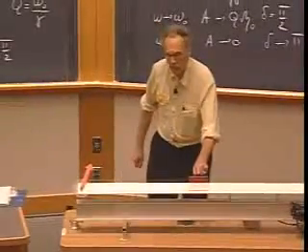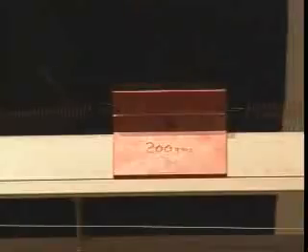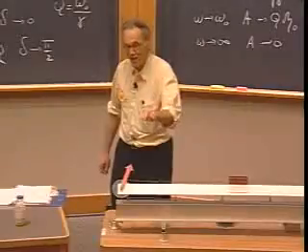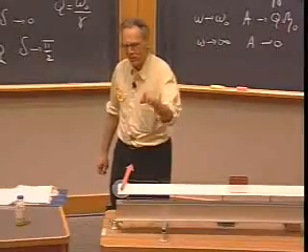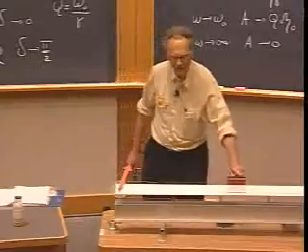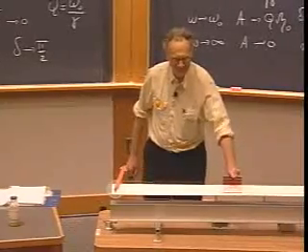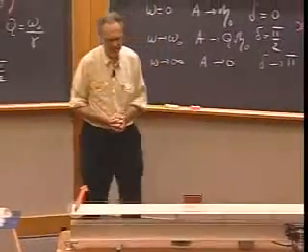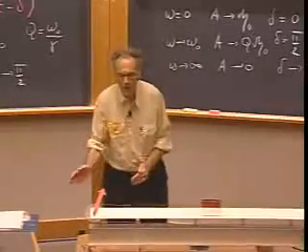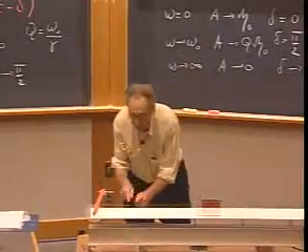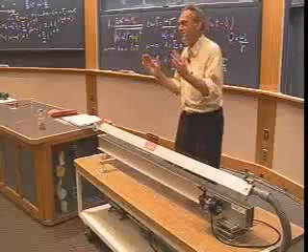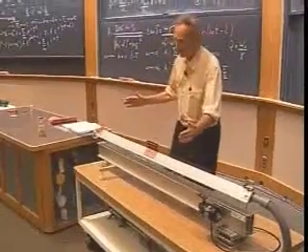What do you think the amplitude of this object will be at that very low frequency? Half of the amplitude of the driver. Very good. Not eta 0, but why is it half? Because we have two springs. So effectively the spring constant is twice that. Exactly. So if I go very slowly, you will see that this displacement here will be twice as high as this displacement. But what I really want to show you is they're in phase. This one will go to the right when this one goes to the right.